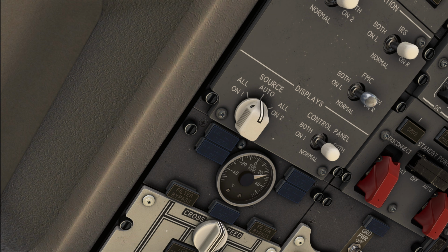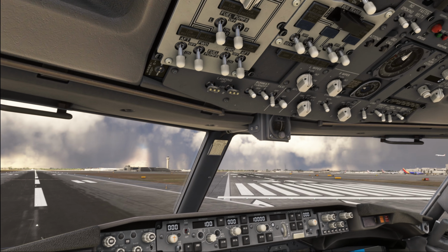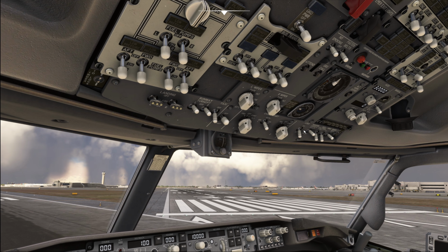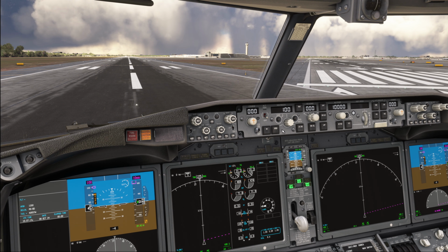Now, due to the engine taking quite a bit longer to start, there is a new limitation on the engine starter motor. While on the CFM56-7 engines that were fitted to the Boeing 737NG, the starter limit is a maximum of 2 minutes, due to the longer start attempt on the 737 MAX, the limit has been increased to 3 minutes. Now, the CFM LEAP 1B engine has the following ground operating limitations.